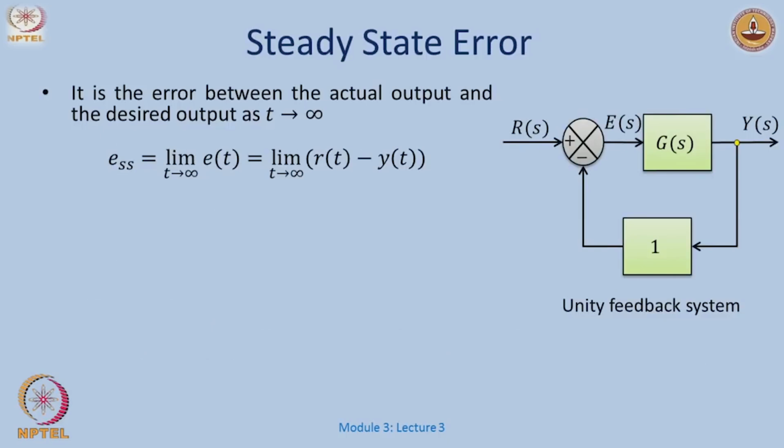Okay. So, once we do these things, we are also interested, does my output follow the reference all the time. We saw last time when we were doing the response for a first order system, in some cases we saw that there is a steady state error, which means the reference is not tracked directly by the output, but it is with some error which was defined by the time constant, right.